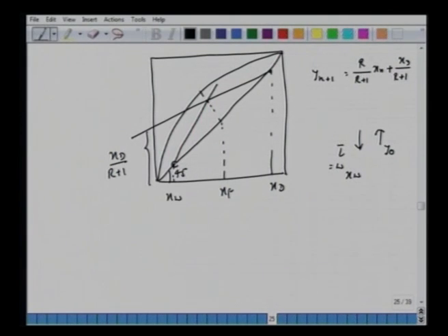In the previous case, when you wrote the expression for the operating line as Ym plus 1 equal to L bar over G bar Xm minus W over G bar XW, when you substitute XW here, this line will also lie on the 45-degree line, so Ym plus 1 will be the same as XW. That's why we extended this to this point.